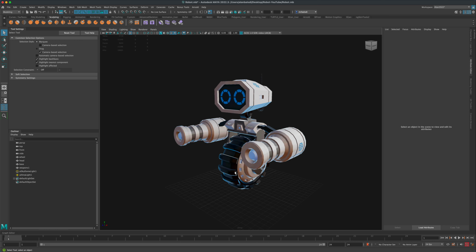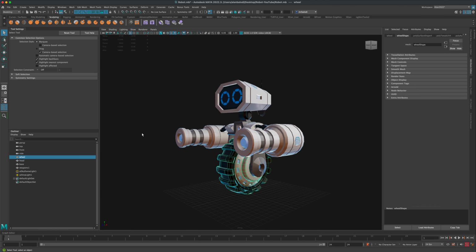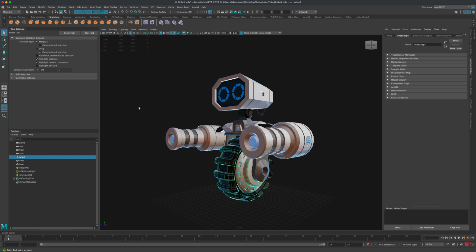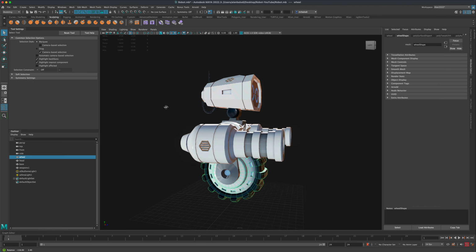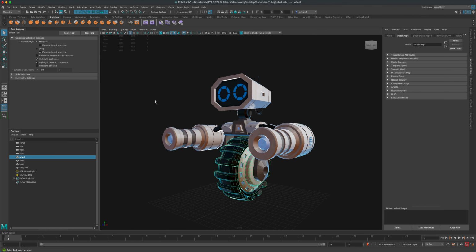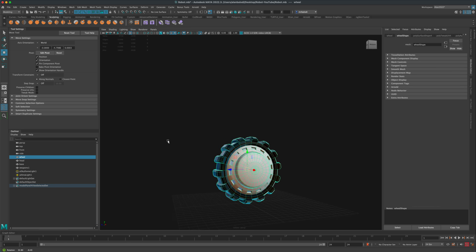And to do that, the first thing we need to do, if we don't want to use joints of any kind, is set your pivots to make sure that things are rotating at the proper pivot, right? So for example, if I click on the wheel and isolate it, then go to my move tool, I can see exactly where my pivot is set.